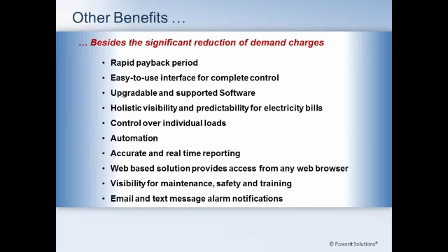The system was web-based, so we could look at it anywhere within the facility. So if we were having a meeting up in a front conference room, we could pull it up and look to see where things were at, how the furnaces were running, what kind of interference we had received due to demand control and demand management. That would allow us to forecast where we wanted to operate for the coming month based upon sales forecast. We may raise our set point number higher. We may lower the set point number based upon business climate and business conditions.